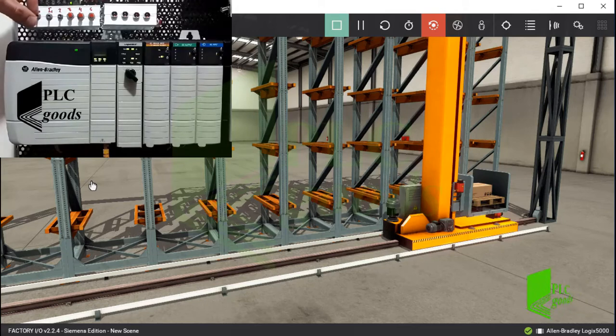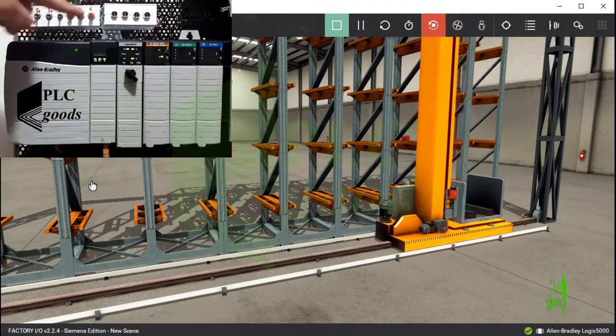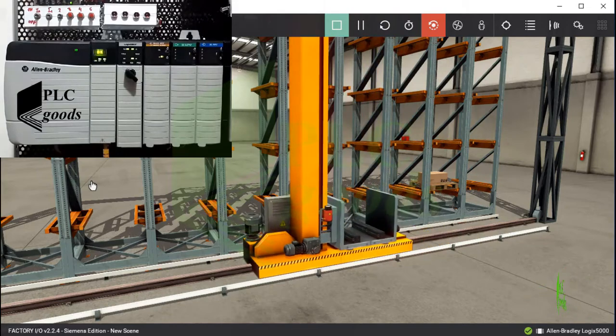Now, I can use my real digital inputs to control the crane and put the box on the desired position. Note that the inserted stacker crane accepts numbers 0 and 55 too. Number 0 won't change the crane position. Number 55 sends the crane back to its default position, where I can drop a box on its arms. So, let me press the 5th digital input, because I used that inside my PLC program to move number 55 to the stacker crane.